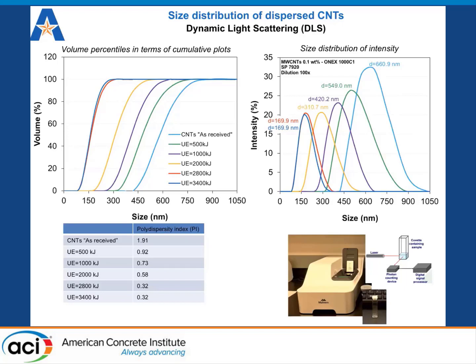From the figures in our slide, you can observe though that the dispersions treated for a short ultrasonic time present a bimodal and broad distribution, and this is an indication of a heterogeneous particle distribution. But with ultrasonic treatment time, the dispersions get more homogeneous and size distributions are narrowed.